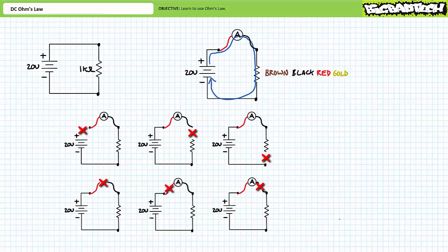As some general advice to aspiring technicians, I will be so bold as to proclaim that fully 99% of all electrical problems you will ever encounter in the field are the result of open circuits. Either some wire wasn't properly tightened on a screw terminal, or it was properly tightened and shook loose, got pulled out, or got cut. Last but not least, do not rule out the possibility of improper use of instrumentation being the source of your problem.